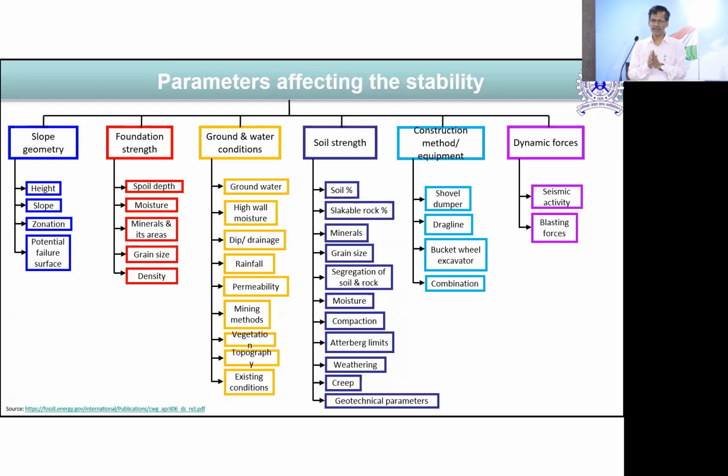Okay, there are different ways of strengthening. First, when I was talking to him, I tried to answer about reinforcing the foundation, that is the first pillar. Similarly, we can also do strengthening of the slope. But strengthening is what we do when there is an existing natural slope. Here I have to revise my design to take care of it. In general, by default, we do benching, or suppose, zigzag benching. That is the way we can avoid these translational slides. Okay, I'll come to that.